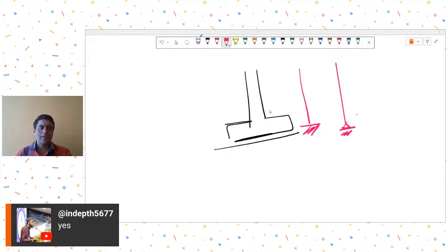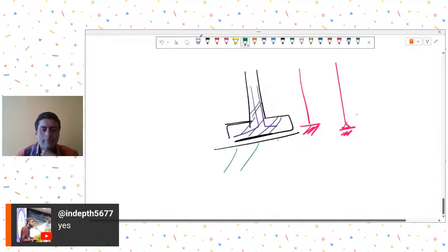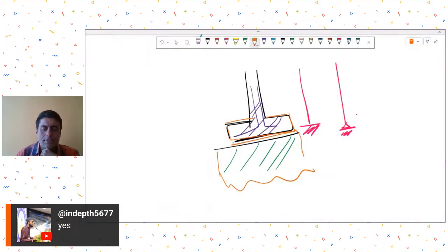So that is a mixed opinion. Some people say that because this is a cast-in-situ monolithic joint that we are preparing, because you have developed your reinforcement to LDT and LDC, and because the support provided by the soil mass is such that in normal conditions there is no rotation as such possible, therefore many engineers and many books that you can see allow you to have a fixed-like support.